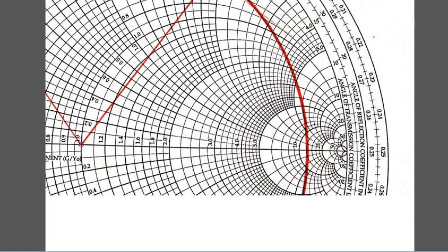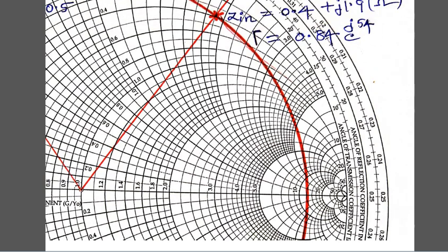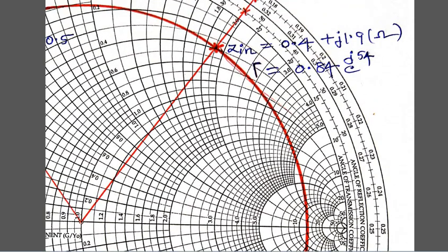By this way we can calculate so many parameters about the transmission line. What are the parameters given? Lambda is given, Z0 is given, ZL is given. From that we went through normalization. Then we drew a VSWR circle, and that tangent was extended onto the scale. We found the VSWR and reflection coefficient.